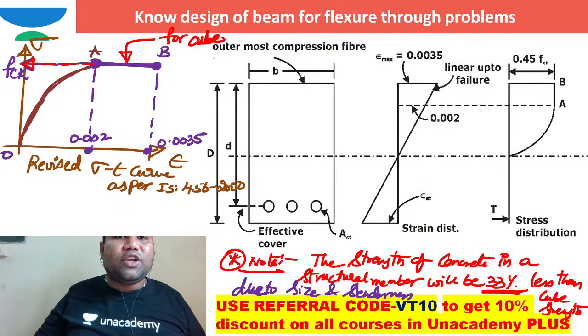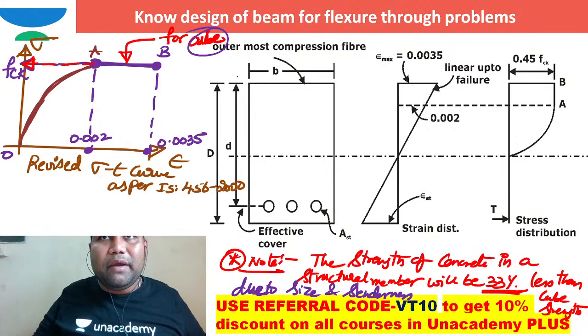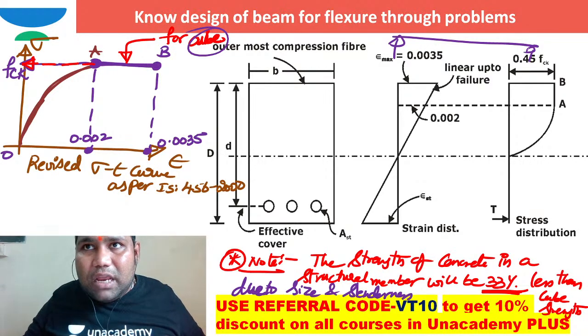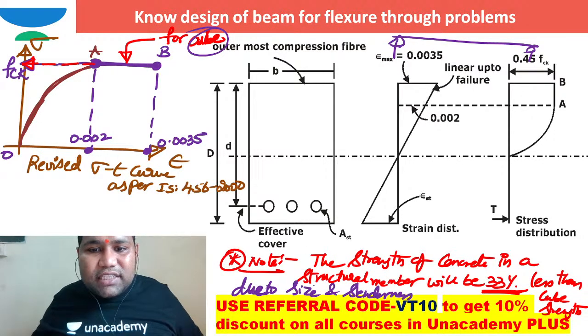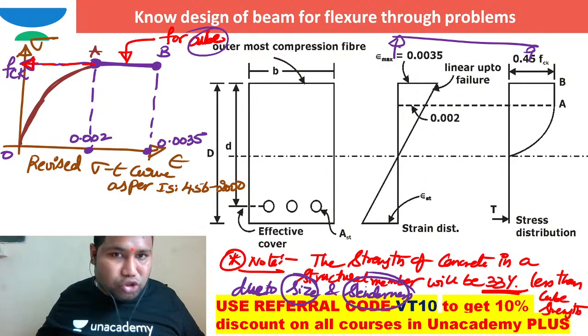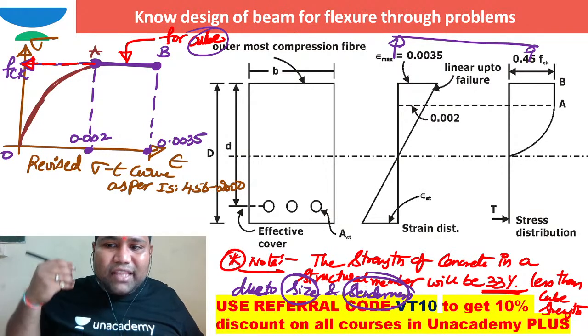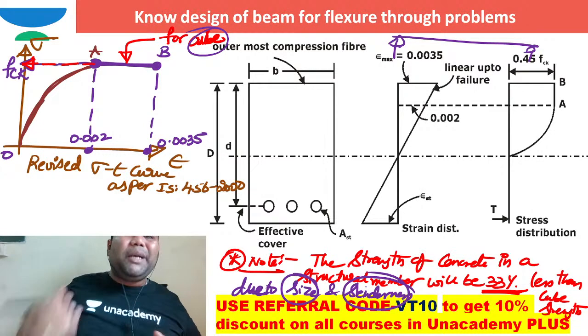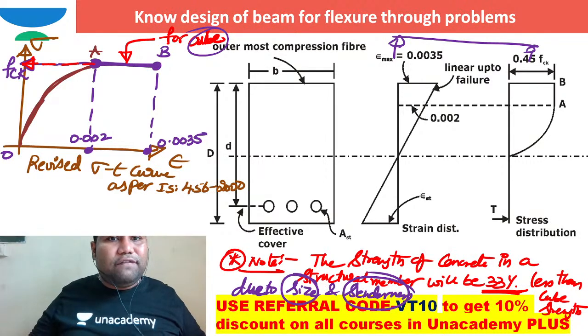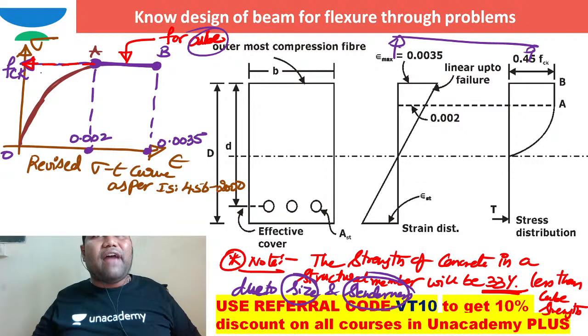In a realistic test, the cube has a dimension of 150 by 150 by 150. But if you take a real beam, the shape of the cross section may be 200 millimeter by 500 millimeter depth, and it also has a very good length. In such a case, there is a size change, and the concept of slenderness effect is also there. Because of this, the strength of concrete in a structural member will definitely be less. And how much percentage will it be less? 33 percentage less. So FCK divided by the partial safety factor for shape and size effect.